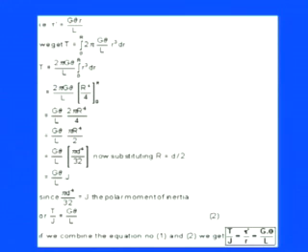And r dr was already there. So now we have 2 pi G theta by L r square dr, or r cube dr. We can simply take the constant terms outside: 2 pi G theta by L. G is the shear modulus of rigidity, which is a material property, and theta is the angular twist. Once you measure the angle of twist, it is constant, and L is the length, which is constant across the body, even under the application of load.